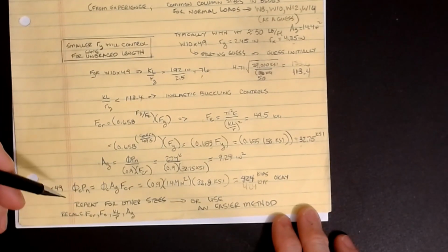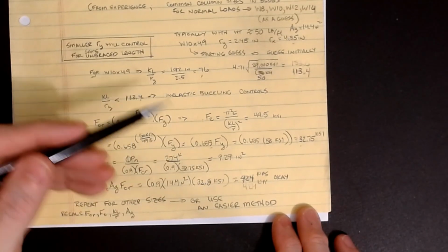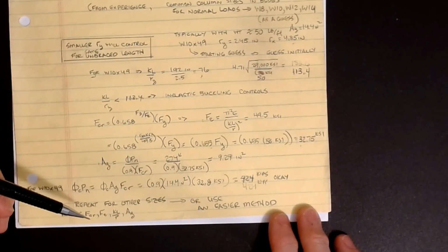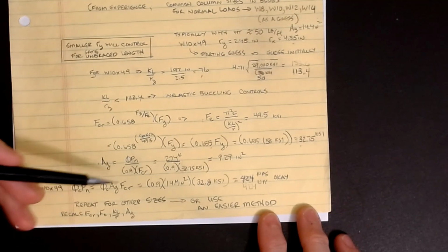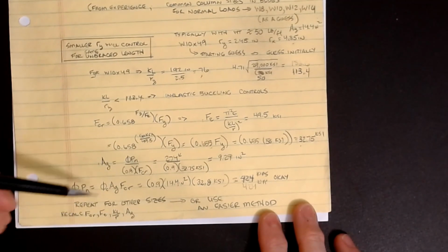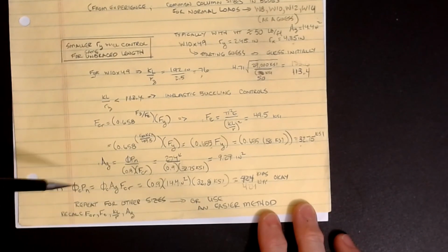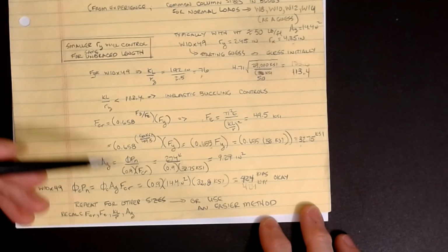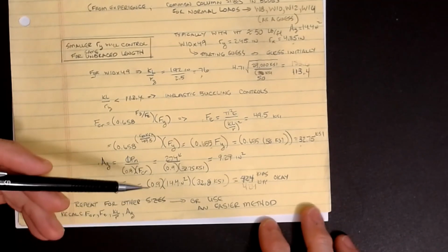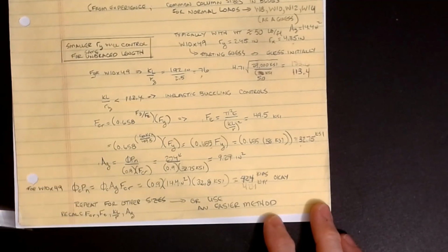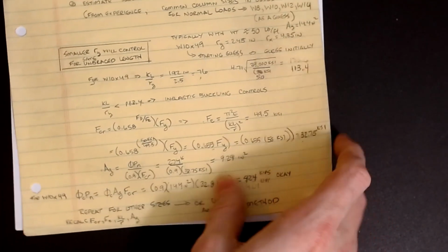All right, now obviously, that's a bit over designed. I would probably want to try something a little bit lighter. So maybe I only need a W12, or sorry, a W8, or a lighter W10, whatever the case may be. But we could recalculate Fcr, Fe, KL over R, and AG by trying another size. Or you can automate it. This is a real good one to put into a macro or a program that contains the AISC tables. You could iterate through and find the fastest one. Or I can show you another method, and I will show you two of those in the next video.